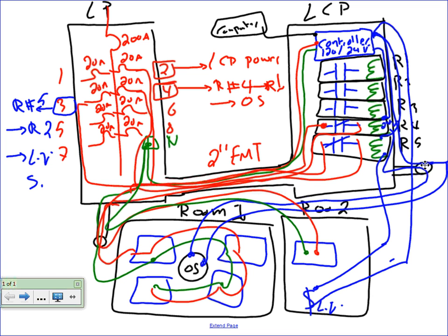A power pack is just, see that relay here? Just that relay in a box. Just one relay in a box. And they put the box right in the center of that room. Just one box with a relay and a coil, right? So imagine, take a second. Take this relay, relay number 5, the coil and the contacts, and take them out of the panel, put them in a box, and call them power pack. Put them in the ceiling, mount them to a junction box in the ceiling, and then interface the occupancy sensor with that box, and that will give you local control in this room without a lighting control panel.